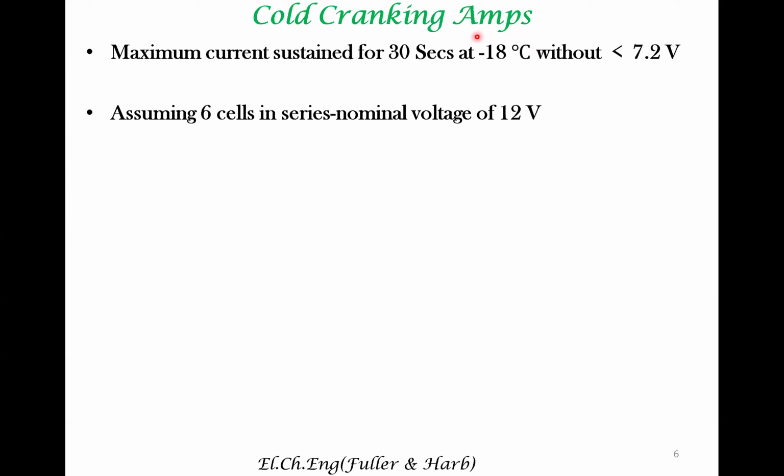This is true of, let's say, winter in the West, or even probably in Jammu and Kashmir. Probably you can get to a very low temperature. So the battery should be capable of operating at very low temperature, where the resistance would have increased significantly.